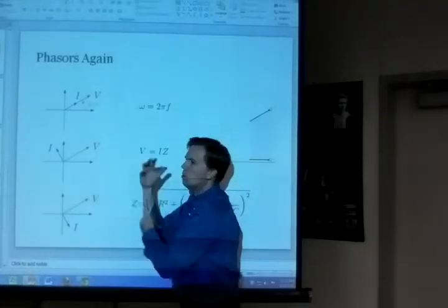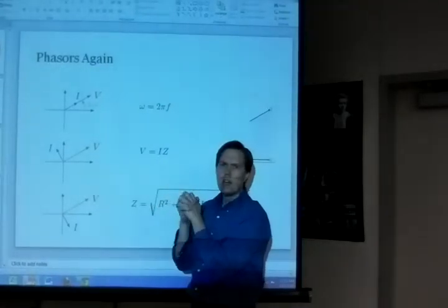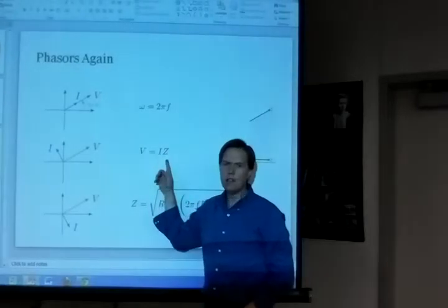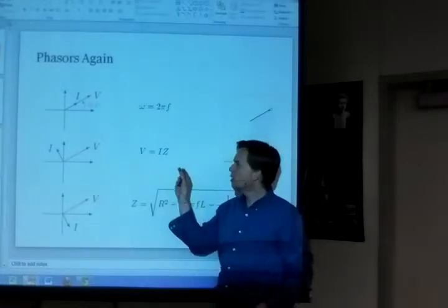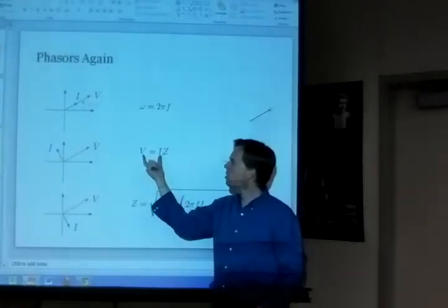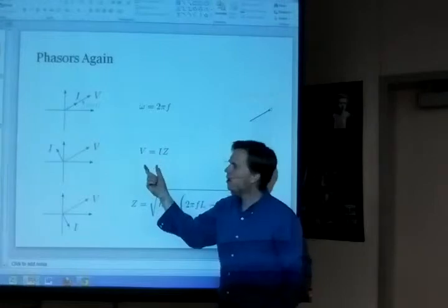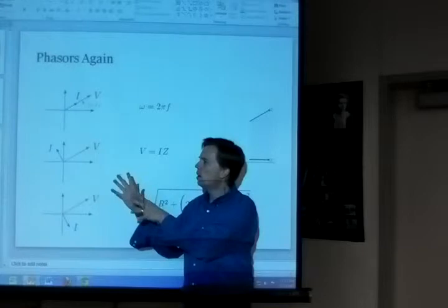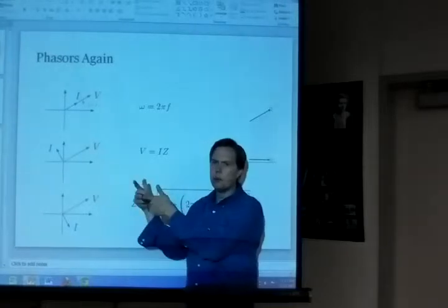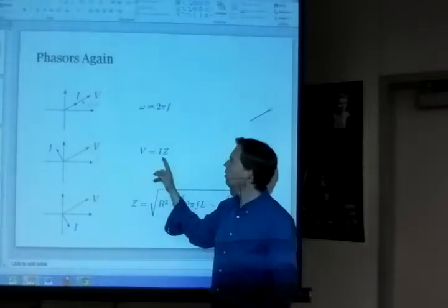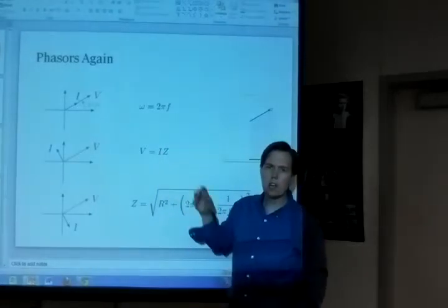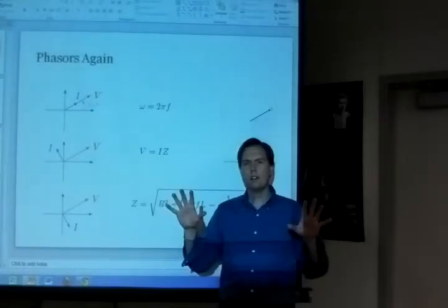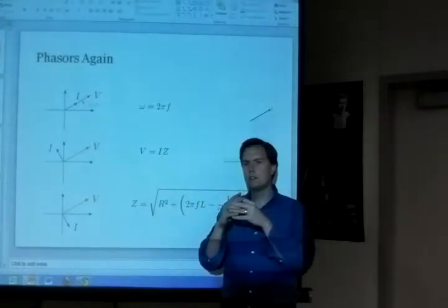And ultimately, when we combine our electric circuits, what we want to capture is the net impedance. And that's what this Z symbol represents. This impedance is the ratio of the voltage to the current. Right? These all move with the same frequency, so they all have the same kind of orientation differences as we move through time. And the total net impact of everything is captured in this idea of impedance. Both resistance and reactance is captured in impedance.